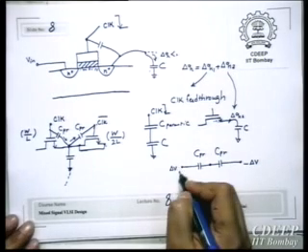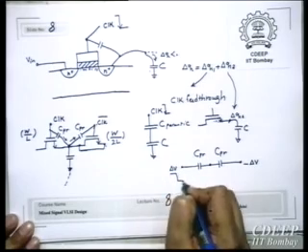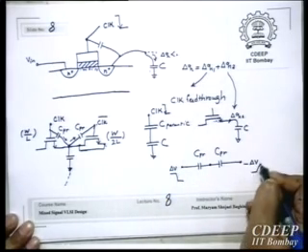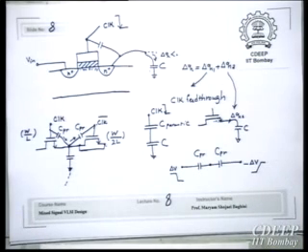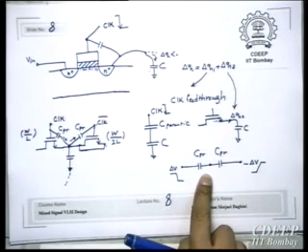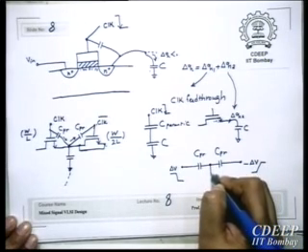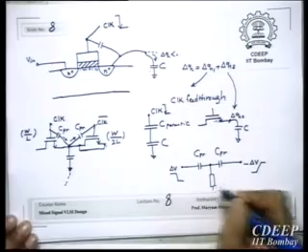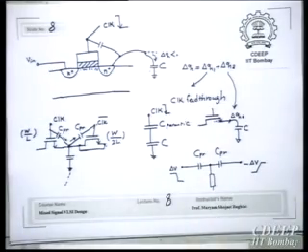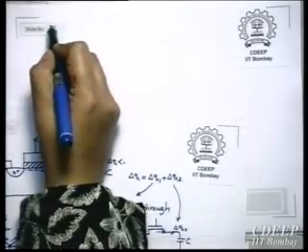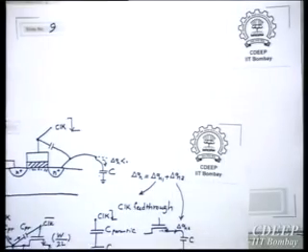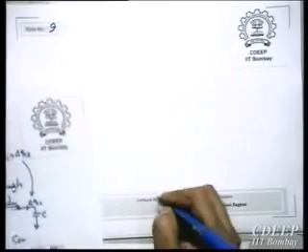So you have a delta V, for example negative here, and a minus delta V positive here. Look at it as an AC signal. Now the common mode of these two AC signals will be 0 because this is a symmetric circuit. When this is 0, what does it mean? It means that whatever is connected here won't see any change, and therefore no current. So always it is preferred that whatever parasitics we have, and they are important, should be discharged to ground.